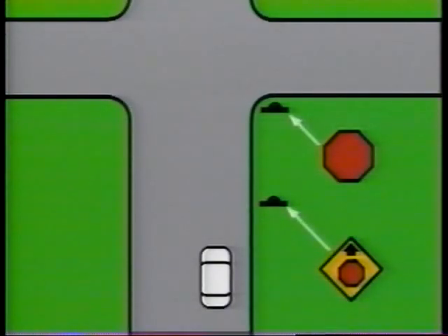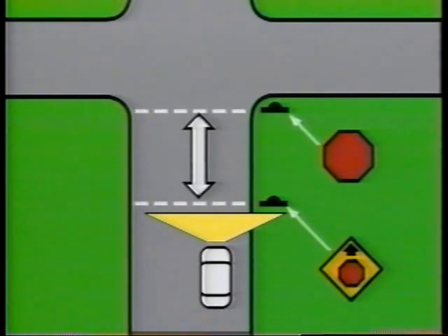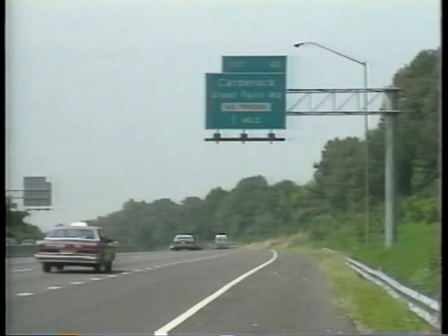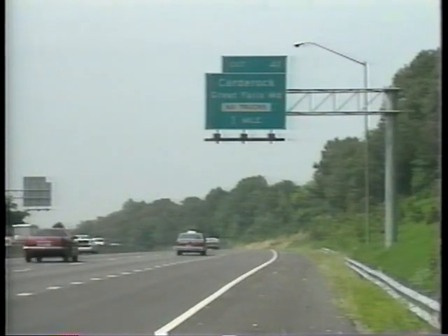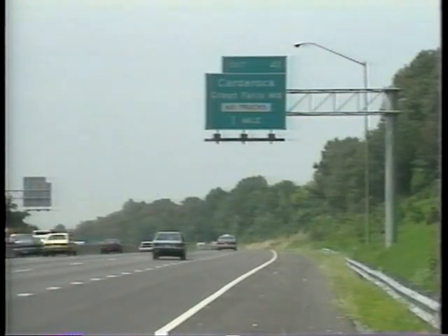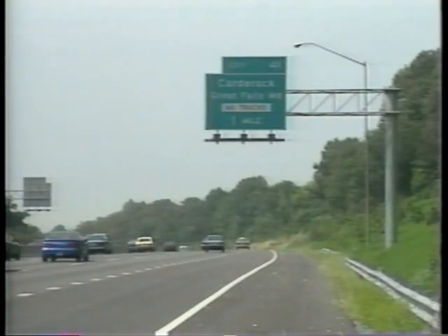There are two basic rules for placement. Make sure a sign is within the driver's cone of vision so that it will command attention, and make sure it is properly positioned with respect to the point, object, or situation it applies to so that it will convey the proper meaning. The term location refers to how and where signs are situated.